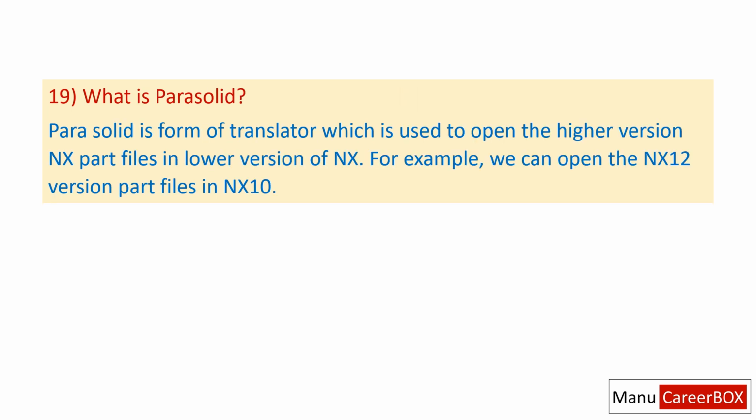19. What is parasolid? Parasolid is a form of translator, which is used to open the higher version NX part files in lower version of NX. For example, we can open the NX 12 version part files in NX 10.